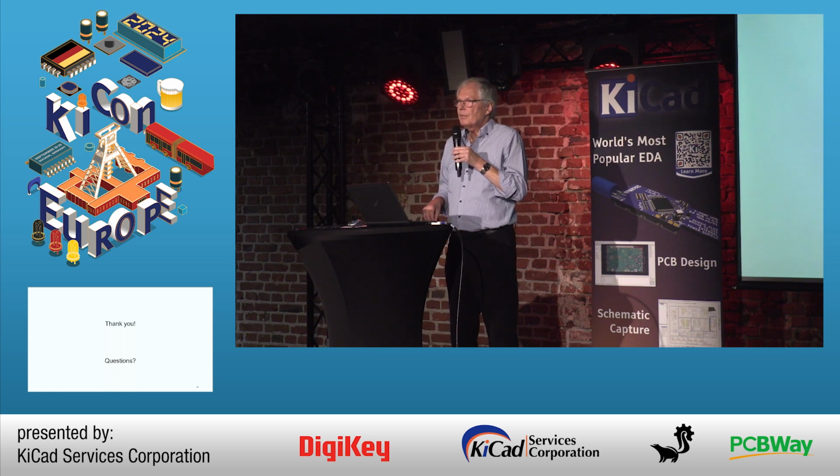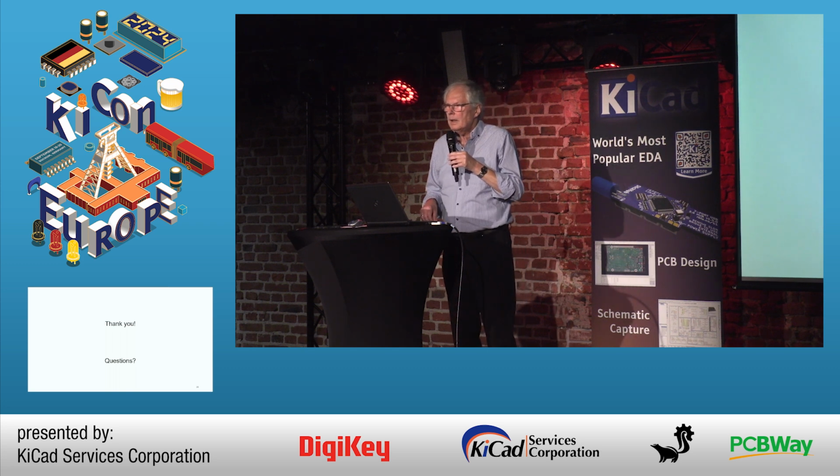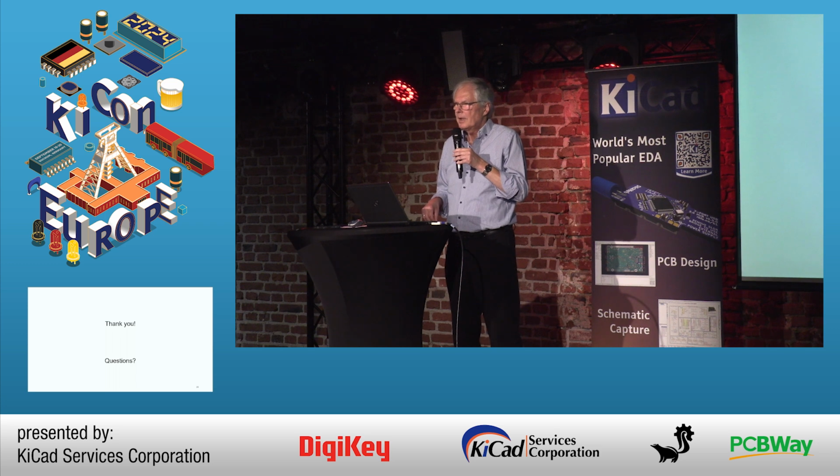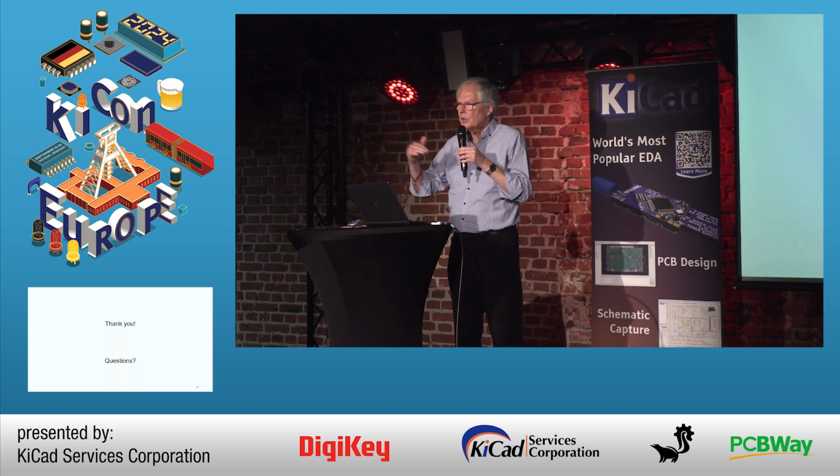Yeah, the first idea, of course, is not to intrude into the models, because these models are so complex that this would be risky. Now we have a look at the model parameters. What is degradation? For example, with radiation, ESA and co, the mobility of the transistors goes down and the threshold voltage shifts. This can be expressed in a parameter shift.